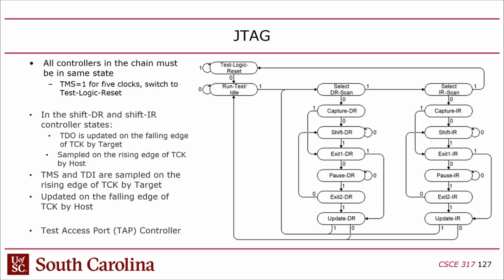And then of course there's TDI and TDO, which are the input and output. It's like MOSI and MISO. And that's JTAG. JTAG is nice because it's the way we can debug the FPGAs. That's how Signal Tap works, which we're going to use later. It's also how the console works and how we program the FPGAs. All that stuff runs over JTAG.